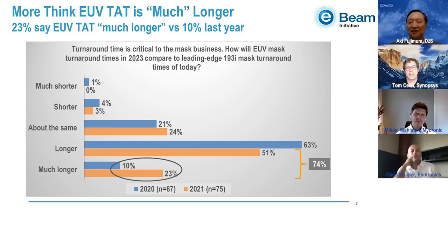Yes, definitely. Everything is smaller. If you take something that used to be double patterning and shrink it down, all the features are smaller. And the writing and inspection and MRC and all of the tolerances on the mask are a little bit tighter. So definitely you have to inspect and make sure you're within tighter tolerances.